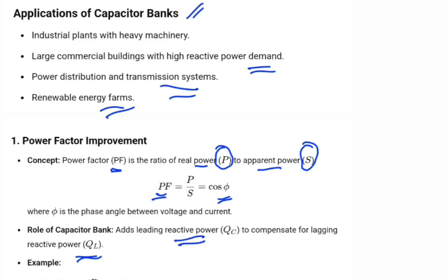So the required reactive power, how much reactive power do we want? It is the root of apparent power square minus real power square. Here the apparent power is 125 and the real power is 100. Now a 75 kVAr capacitor's bank is required for this 100 kilowatt system, right? So now we connect 75 kVAr in the power grid. The 0.8 is now increased to 0.95 power factor, right?